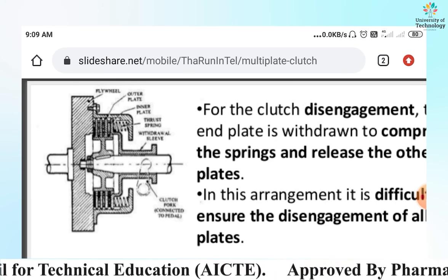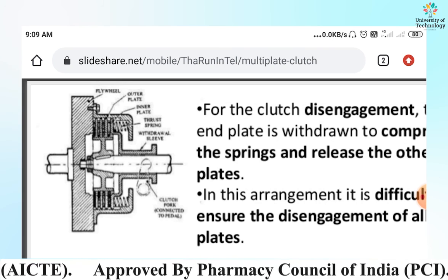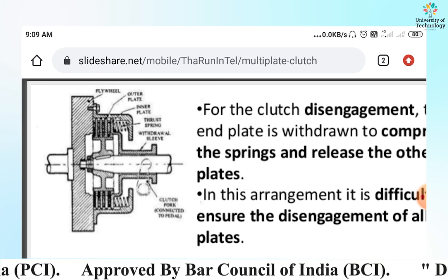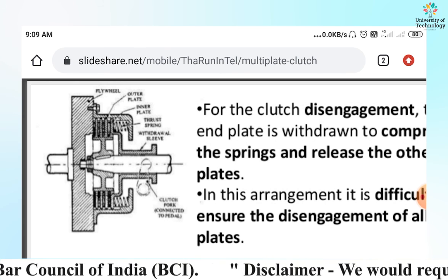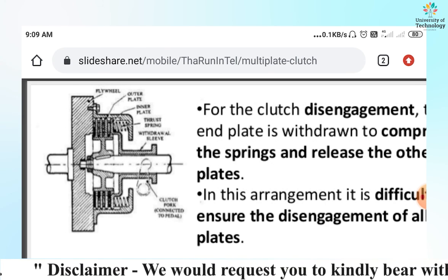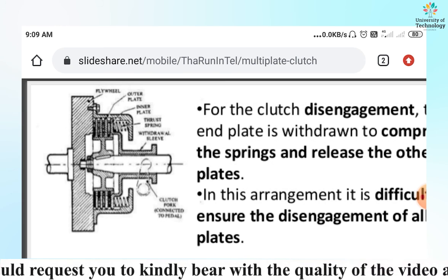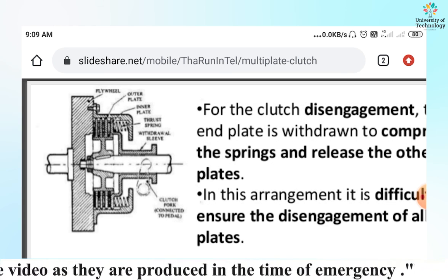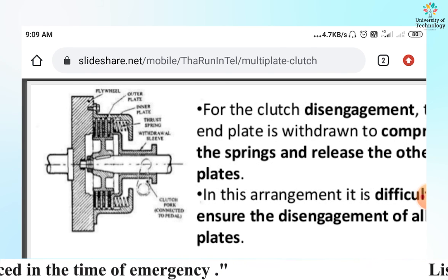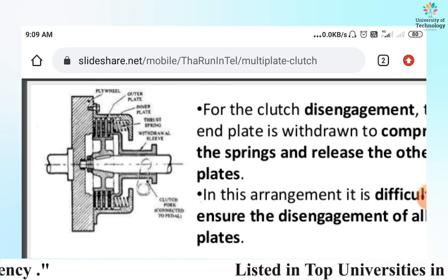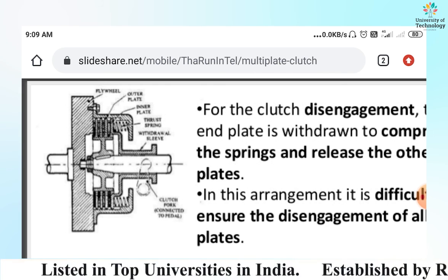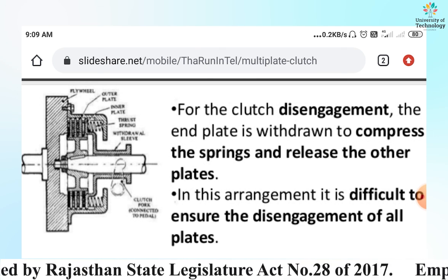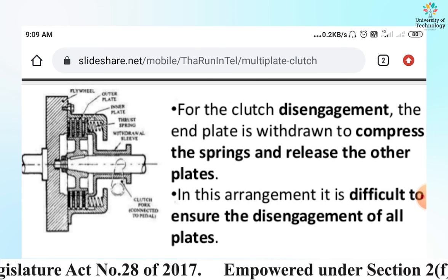A number of clutch plates and pressure plates are used to generate a high quantity of torque in a compact area, and thrust springs are used because when the clutch pedal is released, the spring releases stored energy and the clutch comes into the engaged condition.